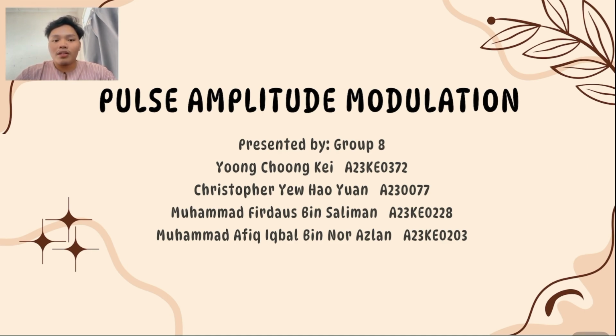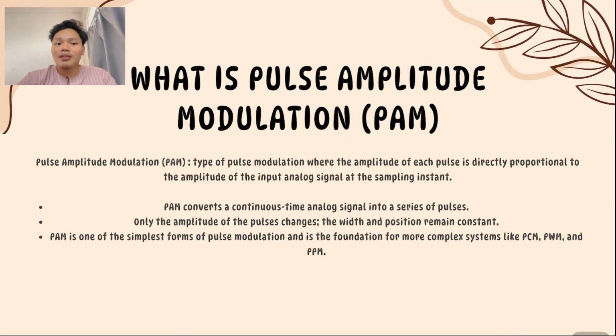We are going to present about Pulse Amplitude Modulation or PAM. What is Pulse Amplitude Modulation, or as we call it, PAM? Pulse Amplitude Modulation or PAM is a type of pulse modulation where the amplitude of each pulse is directly proportional to the amplitude of the input analog signal at the sampling instant.